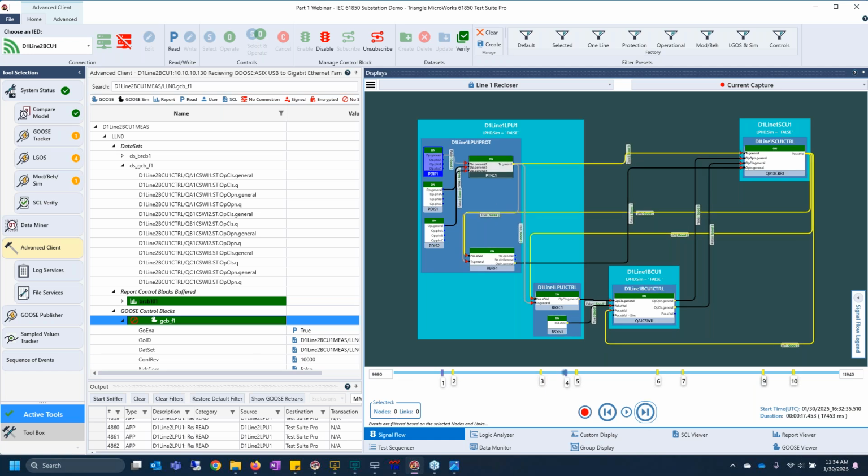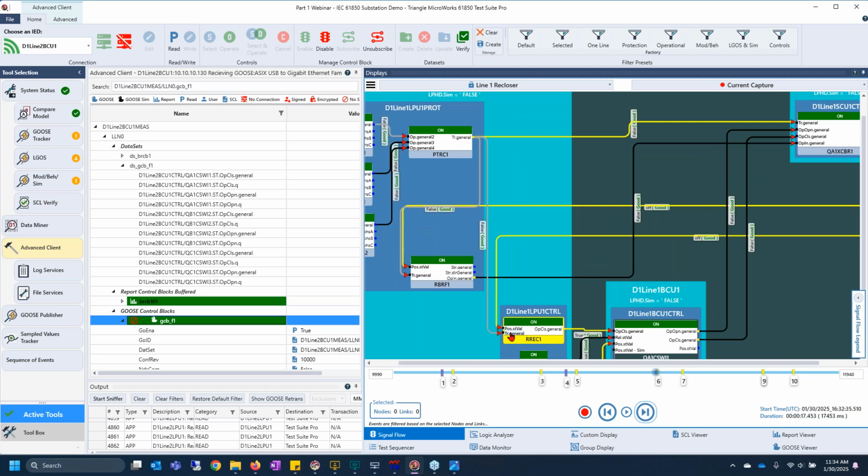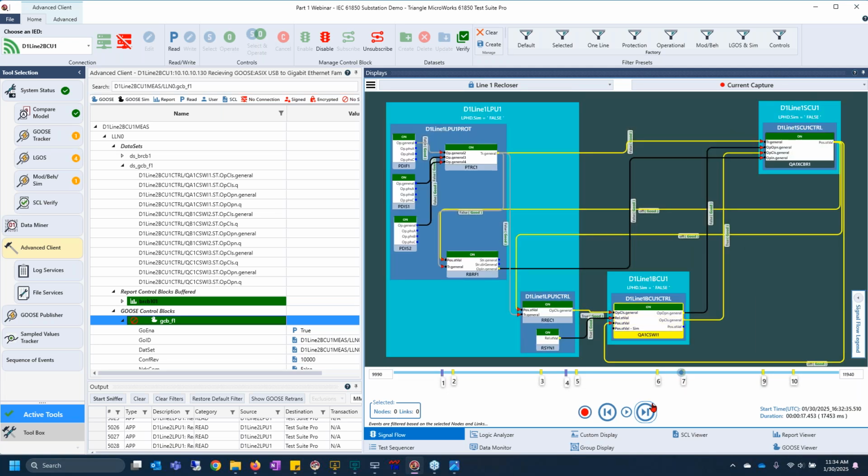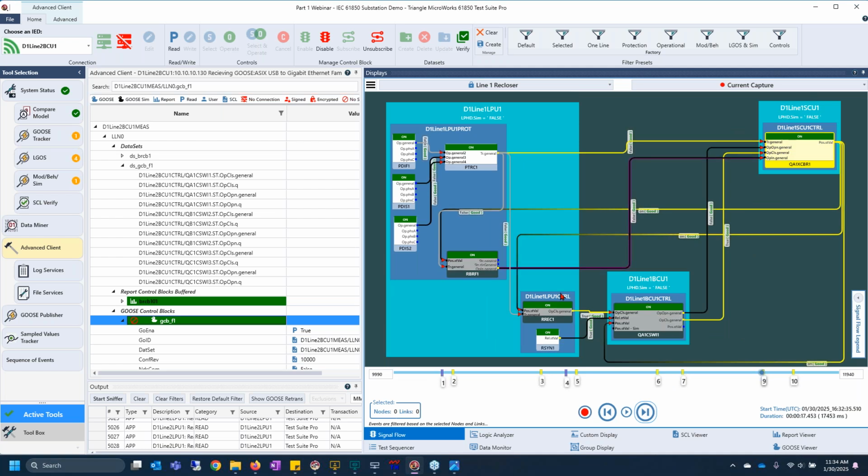The fault then goes low, right? The PTRC goes back low with its falling edge. The recloser says, hey, I noticed the breaker open. Let's try to close it. So the position triggered the op close. The op close then went to the bay controller unit, which then sent an op close back to the breaker. And sure enough, the breaker then closed.